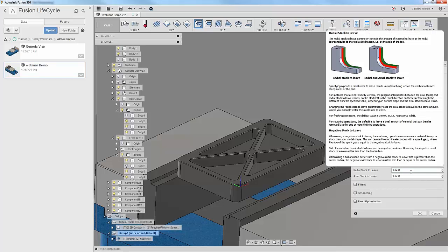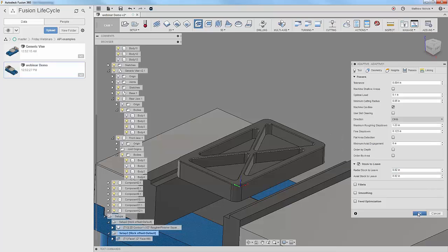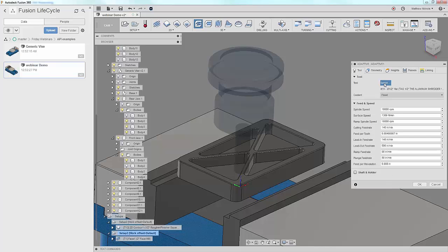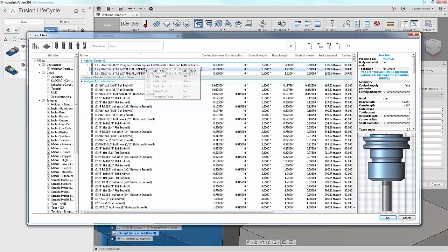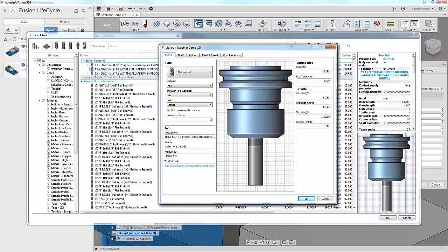So that was the actual tool flute length from the tool definition, right? That's the parameter name? Yep. So if I go back into my library and hit edit, I can come over to the tool flute length, and if I hold down shift and hover over, typically it would actually show the parameter name and all that stuff, but it actually doesn't on the tool library right now.